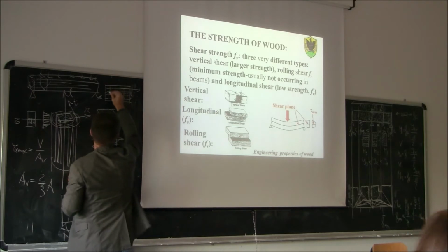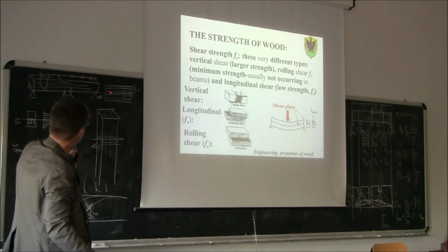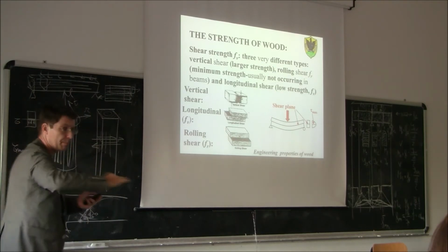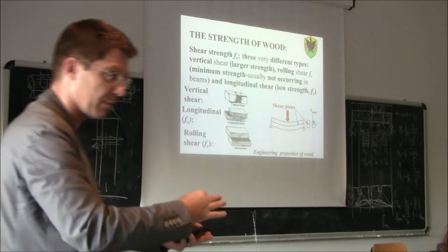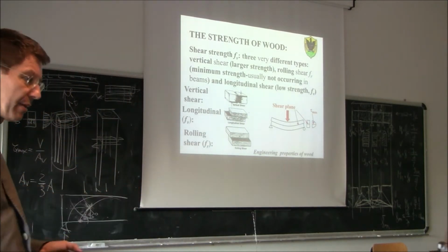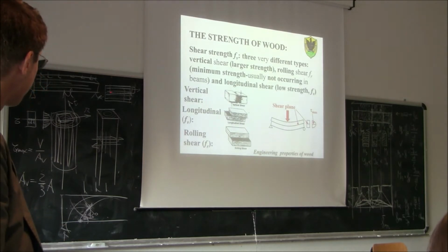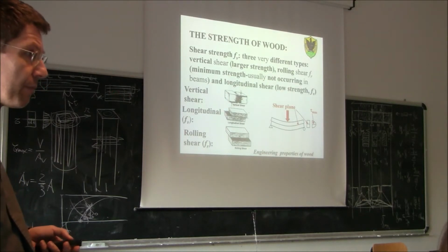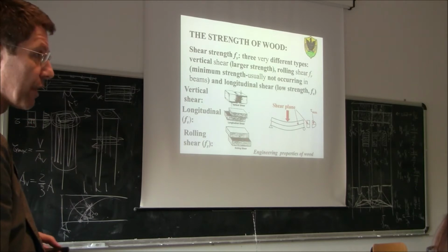This is the weaker plane. So we can expect to have a shearing on a plane parallel to the fiber, because this is actually the weakest plane. In this way we're going to break the middle lamella, so the weak matrix. Is it possible for shear to have a failure like this, since the tau are oriented over the cross section this way?